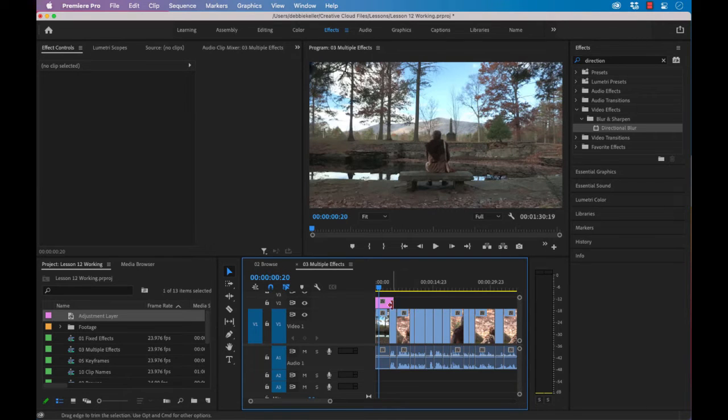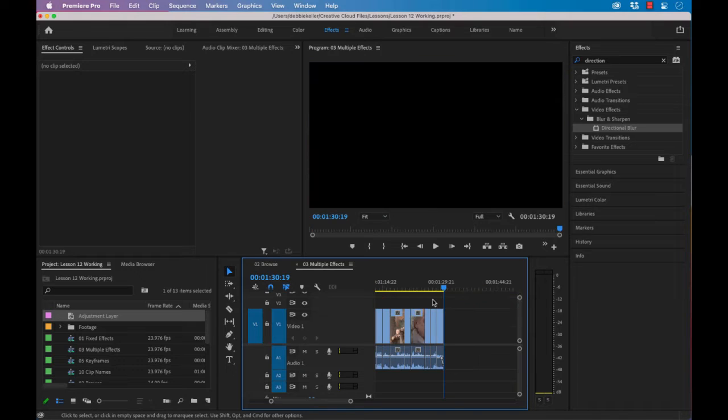Click the right edge of the adjustment layer clip in the Timeline panel to select just the out point. A red trim handle icon appears on the end of the clip. Next, position the playhead at the end of the sequence just after the last clip. You can achieve this quickly by pressing the End key. Now press E to perform an Extend Edit. This extends the selected trim handle to the location of the playhead.